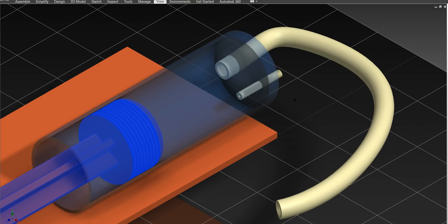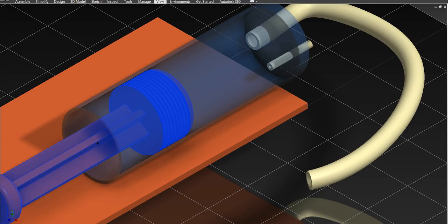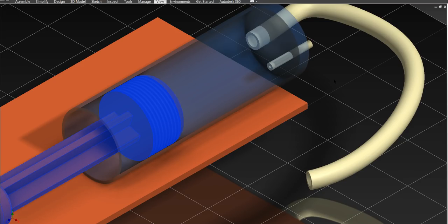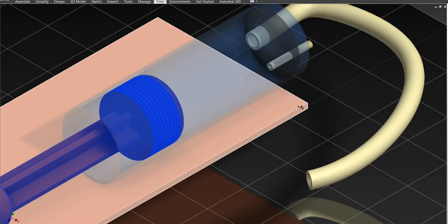There is also an inlet valve that allows the motion of air only inside. So when the compressor piston moves outside, it increases the clearance volume, hence decreasing the inside pressure, as pressure is inversely proportional to the volume. So as the volume increases, the pressure decreases and the outside pressure is more. So the air rushes from outside through this inlet valve into the container.